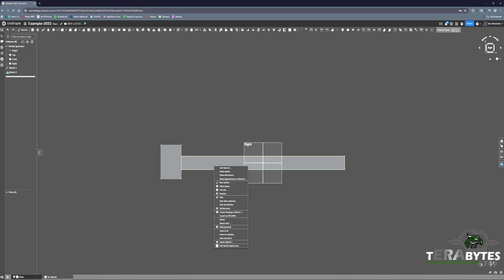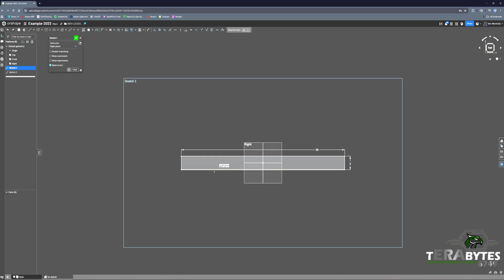We're going to leave that sketch alone, actually. But we are going to go back into editing this one. We're going to add some circles, preemptively for now. Put them there. I said these are going to be 4. I'm going to put them in. And basically what we know is that from the bottom of these to the top of this, our value is going to be, I believe we said, 3.75. So there we go.